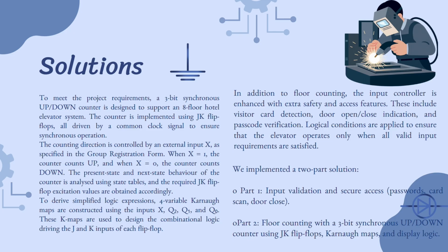In addition to floor counting, the input controller is enhanced with extra safety and access features. This includes visitor card detection, door open or close indication, and passcode verification. Logical conditions are applied to ensure that the elevator operates only when all valid input requirements are satisfied.